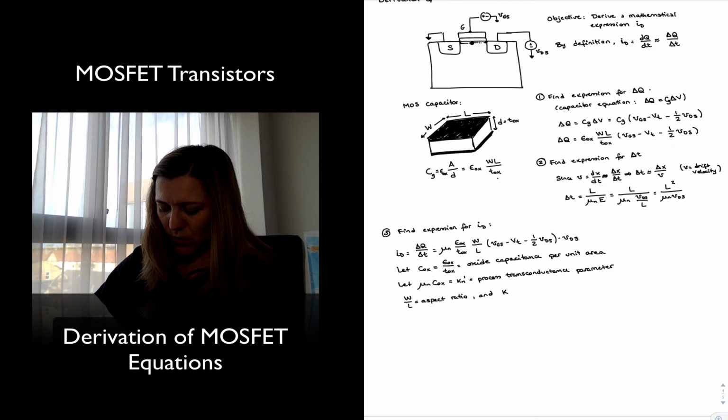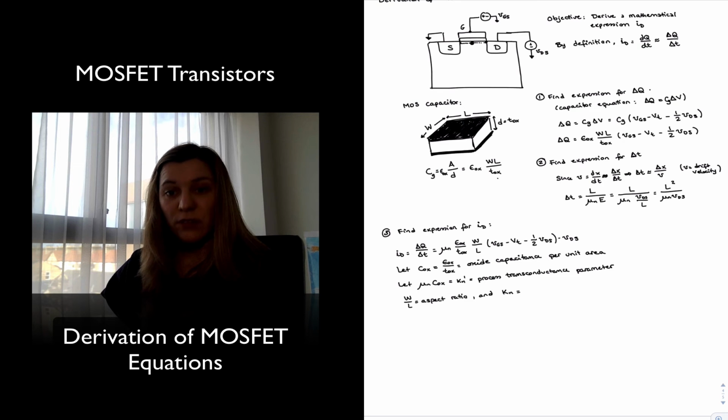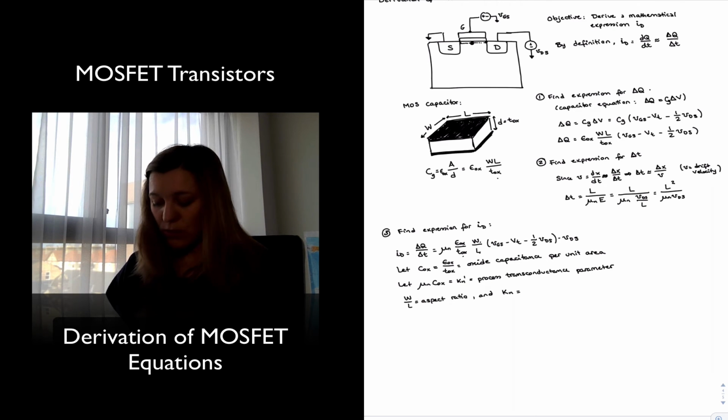And we typically label the transconductance parameter times the aspect ratio as the MOSFET transconductance parameter or the transistor transconductance parameter. Because again, if you look at the overall expression, mu n epsilon oxide over thickness oxide times the aspect ratio, that gives you the transconductance. It will be basically the output current divided by the voltage. And so it has units of current over voltage again.